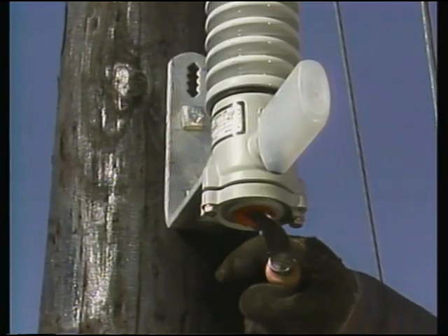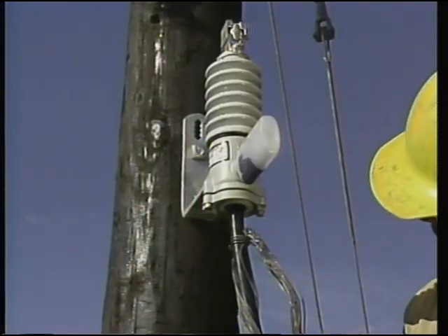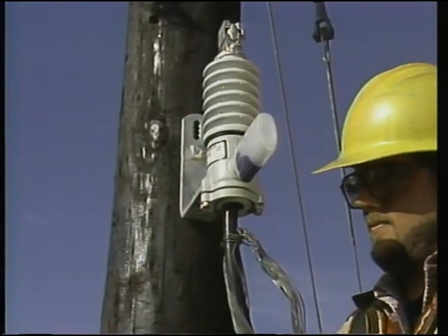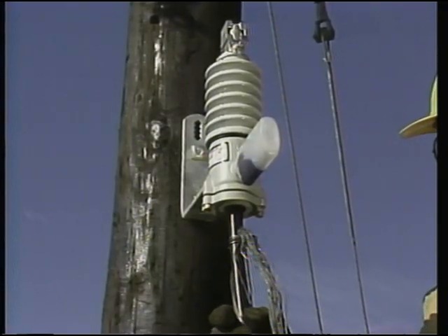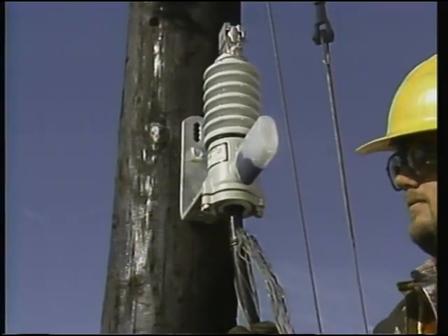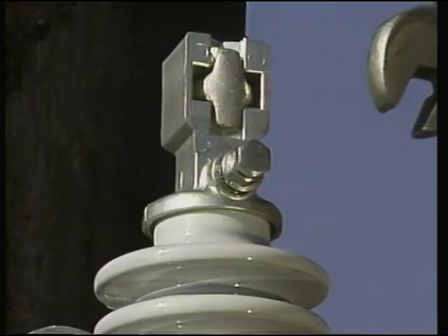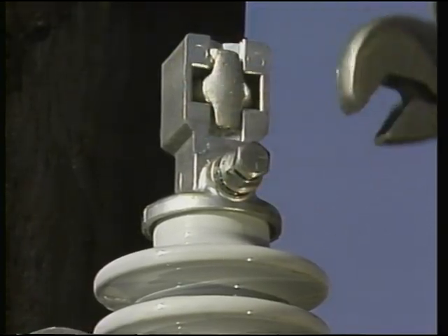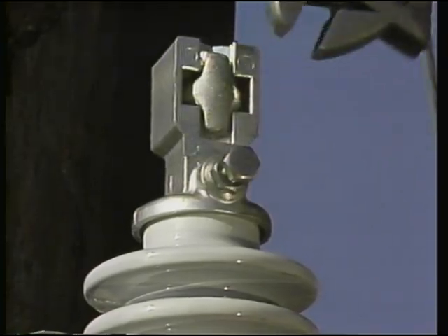To insert the cable, the plug at the base of the terminator is removed. Then, with a constant force, the cable is pushed up until the tape mark is even with the bottom of the terminator's cable entrance. Inserting the cable displaces the insulating fluid from the terminator into the plastic bottle. With the cable fully inserted, the set screw is tightened to secure the cable in the terminator. Then the lock nut is tightened.